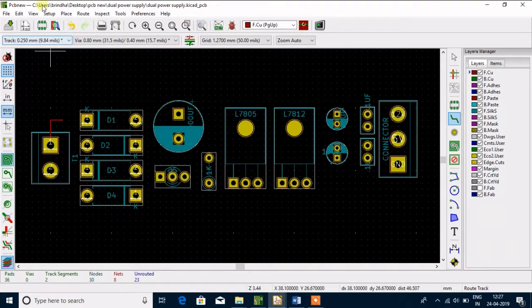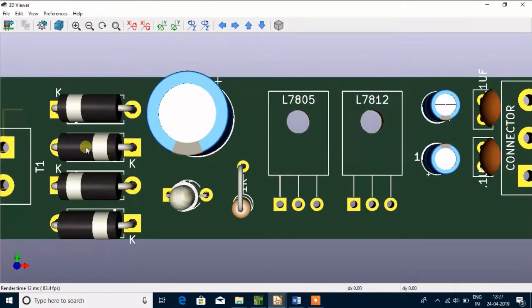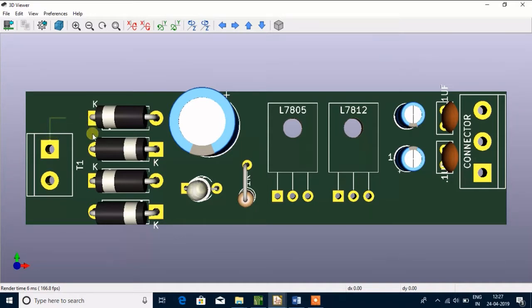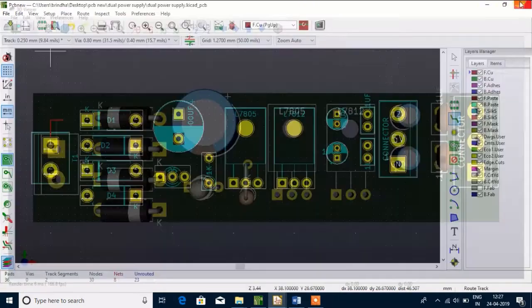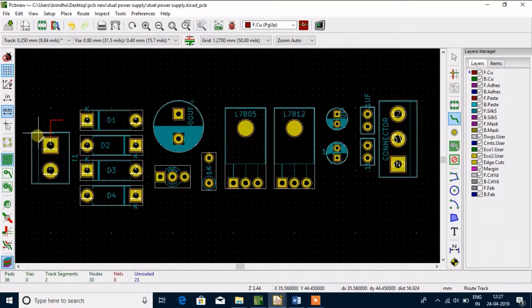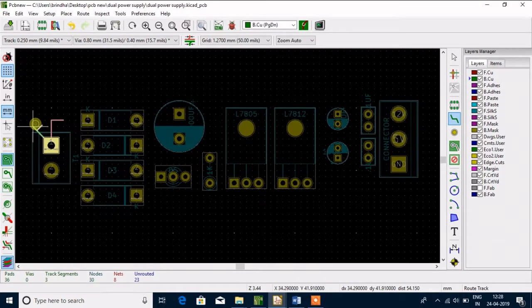The color is something different than what we expect. Let us just see that in a 3D view. You could notice that there is a color present over here and it is something green. Something is wrong in this circuit diagram. So what is wrong in this circuit diagram? Yes, we have to use only back copper, since we are just going to give connection only in the back side, and the PCB that we have designed is a single side PCB or single layer PCB, and we have used almost only through-hole components, and hence just click back copper and again click that.